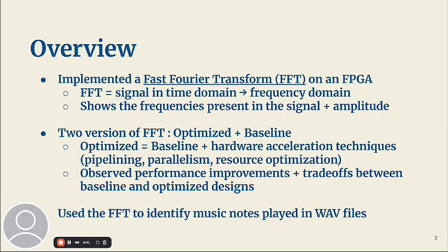For this project, we implemented a fast Fourier transform, or FFT, on an FPGA. The FFT converts a signal from the time domain into the frequency domain, which lets us see what frequencies are present in the signal and their amplitudes.